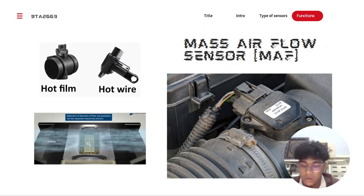The very high temperature coefficient of resistance of these metals means that even very minute changes in the temperature of this metal will change their resistance. So when air flows over the metals, it changes their temperature. The more air flows over, the more the resistance changes, and the onboard electronics of the mass airflow sensor measure this and then convert the signal into useful data for the ECU.